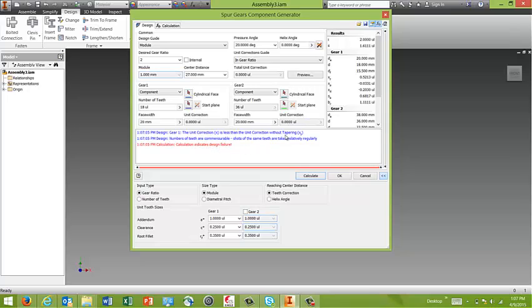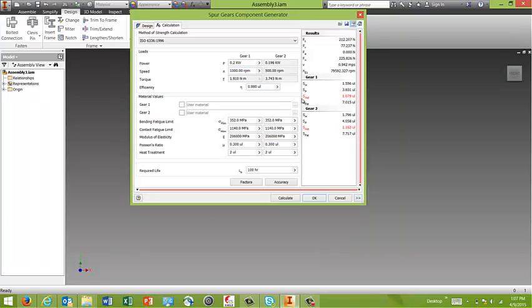And sometimes when this happens, you can actually go to the calculation and you'll see on this window what it is that is failing. You move your mouse over to it and it says that there is a static safety in contact. That means under the static stress, it's really too high. So what happens is that you can go over here and indicate your power, you can lower your power to 0.02 or 1. Let's try 1. And if you were to click calculate, everything goes black, means you're okay.